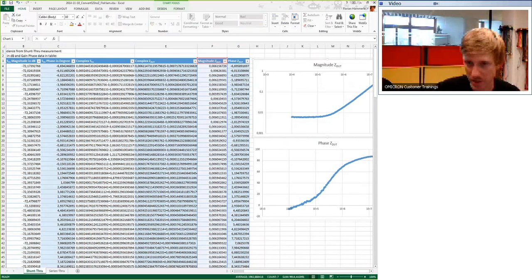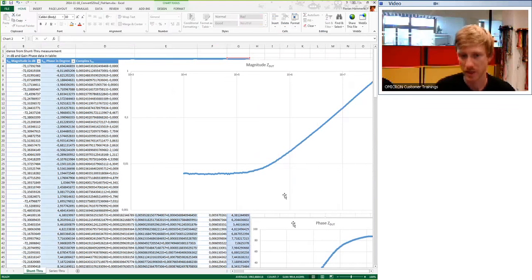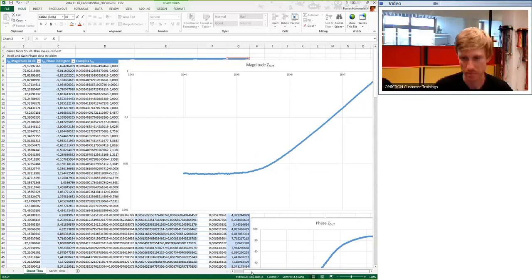So here we already see a diagram that shows me the impedance magnitude. I will resize it a little bit. And we can see that it says at 13.9 kilohertz we have 6 milliohms. So it's a 5 milliohm resistor, and we are measuring 6 milliohms. So we are probably a milliohm off, which is not a lot. And you can see that with this measurement, you can measure down to very low milliohm values. Yeah, and we did not calibrate, so maybe this also has an influence due to the contact resistances that we have for this measurement.